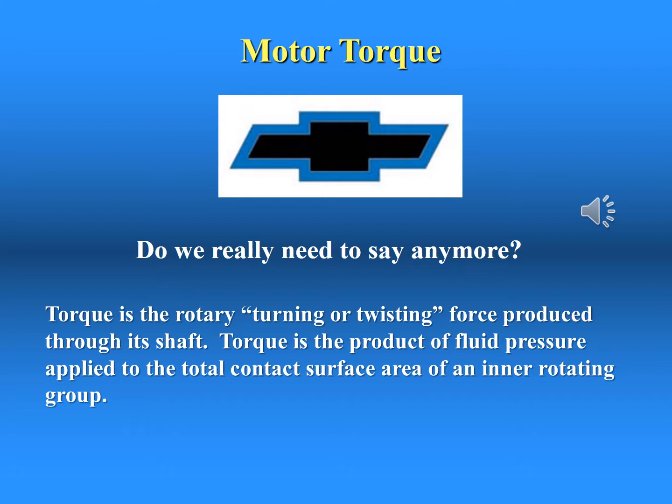If a motor whose displacement measures 0.203 cubic inches per revolution is subjected to a pressure of 500 psi, it will produce 16.16 inch-pounds of torque. For the exact formula, see Appendix B of your lab manual.